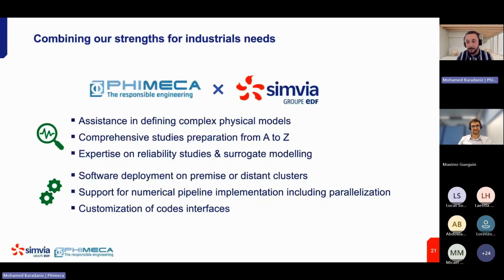But Shaper is the tool to come for the Salome platform in terms of geometry construction. It has new features that are developed continuously. Also, the philosophy of geometry creation is different from Geom, because you find the logic of creating a sketch in 2D and then using all the operations that are available to create 2D or 3D models. That new way is more flexible to create more complex geometries. So that's the reason why.